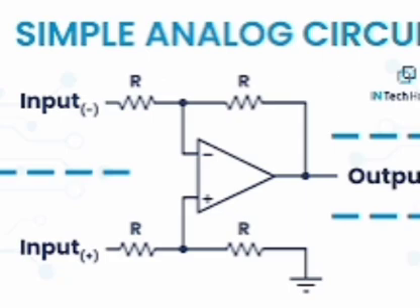IB equals VCC minus VBE by RB, IC equals VCC minus VCE by RC. IB is constant or fixed, hence the circuit is called fixed bias circuit. S equals 1 plus beta, since S is very large, IC will be unstable.